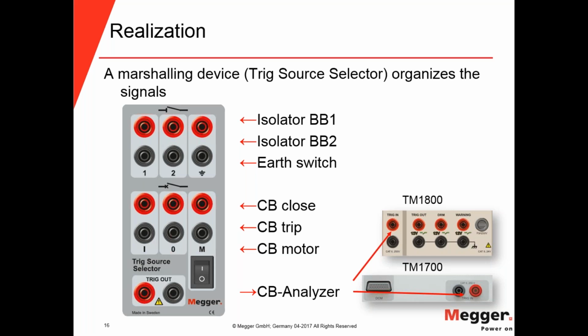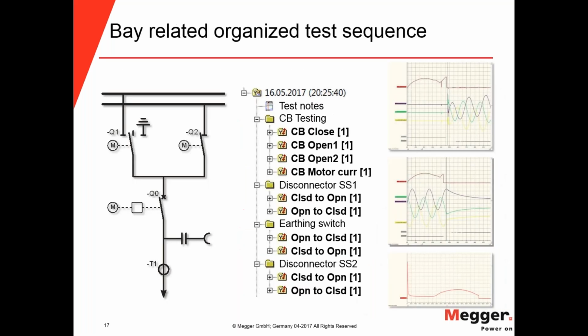In that sense, you can do your connections initially, and then you just perform all your tests according to a bay-related organized test sequence. So you don't need to worry about reconnections during your test. Of course, you have to do some connections. You have to move the current clamps and so on.